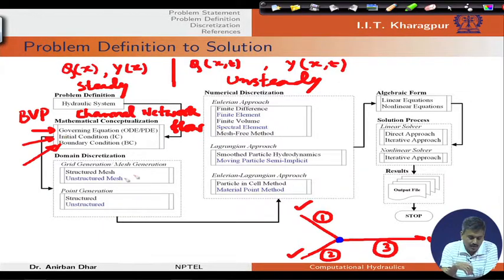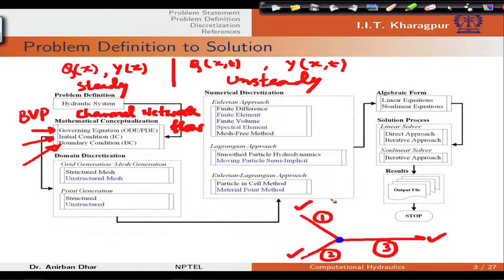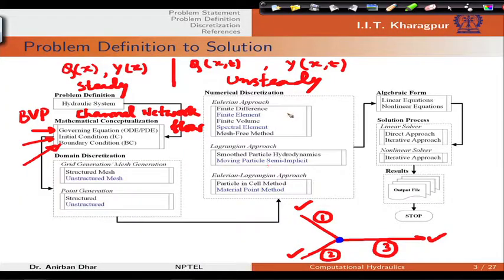Now, we can discretize our domain, which is essentially 1D domain, each channel network channel reach. In this case, we can consider uniform grid. Also, we can solve the same problem for non-uniform grid system, and in this case I will be talking about a special kind of finite difference technique.